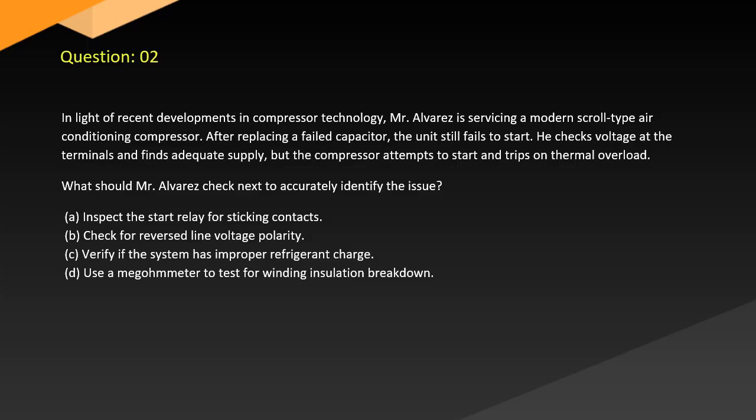A. Inspect the start relay for sticking contacts. B. Check for reversed line voltage polarity. C. Verify if the system has improper refrigerant charge. D. Use a megohmmeter to test for winding insulation breakdown.